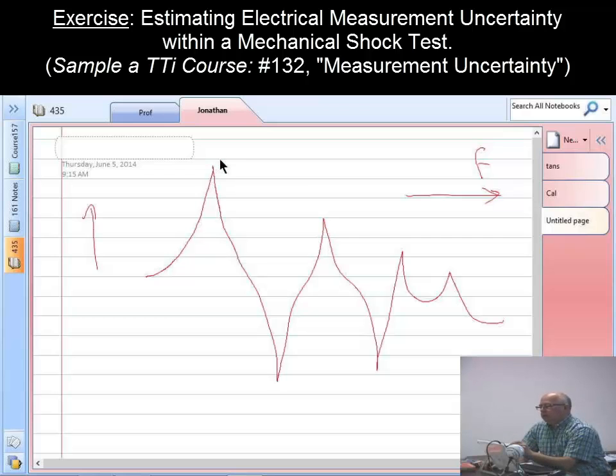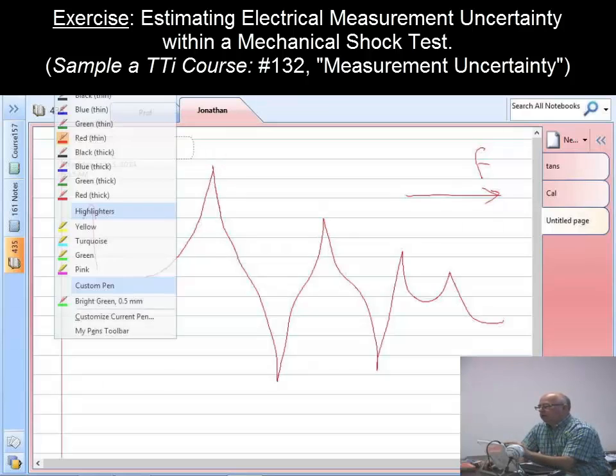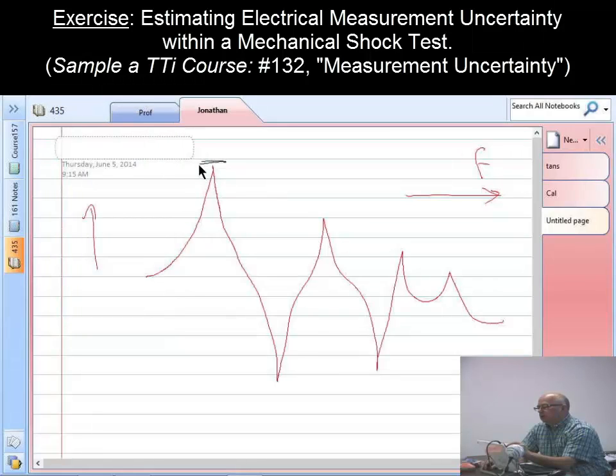With the analyzers that we use, we have to be very careful not to overload, and so the input to the analog to digital converter has to ensure it'll take those peaks. A to D converters notoriously go awful if you overload them. Actually, it's not that the A to D converter can't handle it, it's just a threshold and gives you a square wave out. But the algorithms that we run in signal processing do not like truncated data. So we set that to the maximum.